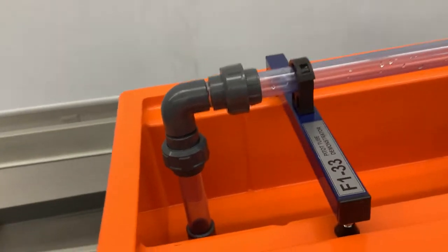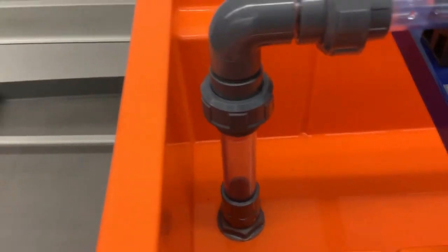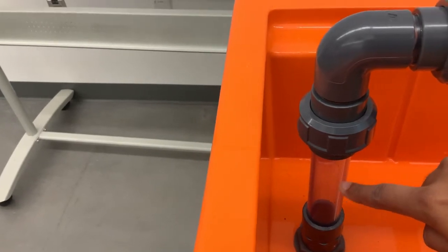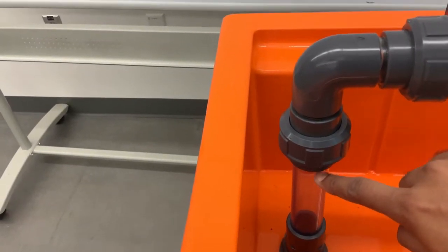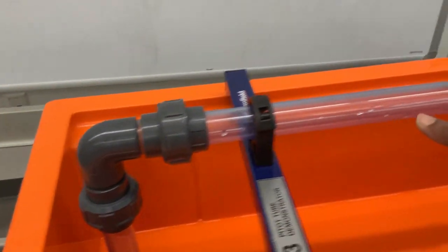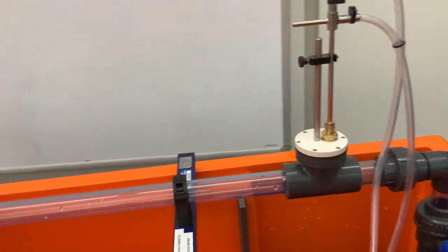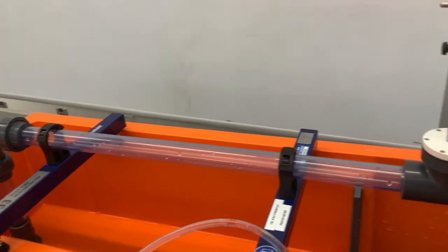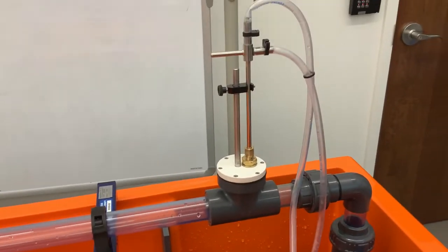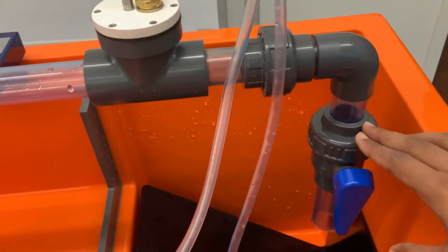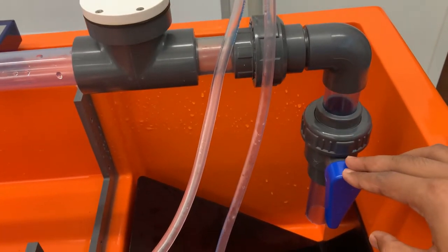I'll show you. On top we have connected the tube, the pump inlet, and the pump outlet, so the water will come in, go to here, and it will go all the way through. We put the Pitot tube far from the inlet so the stream may stabilize and we can get a better result. On the other hand, we have a valve that is fully open.